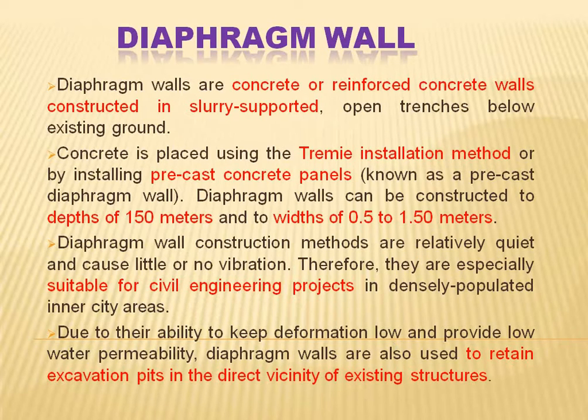Diaphragm wall is a concrete or reinforced concrete wall constructed in a slurry-supported trench. Concrete is placed using the tremie installation method, or precast concrete panels are used. If we construct a concrete wall using precast concrete panels, then we call it a precast diaphragm wall.